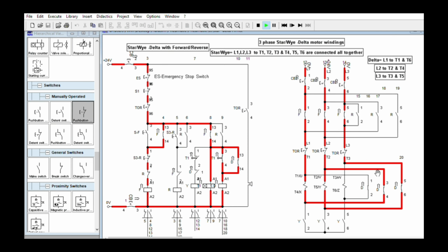Delta. Okay, remember this is not advisable for all motors. You cannot instantly reverse a motor under instant condition and instant situation. Forward. The motor is turning, let's say that way, and we are going to instantly reverse them. There are implications for the shaft mechanism and the load. And the current is very high.